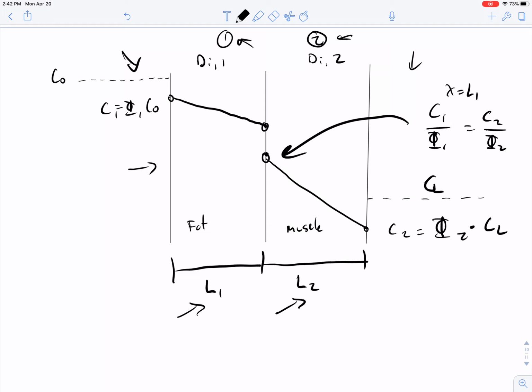What do we do in the middle? What do we do where these two materials meet? We have a balance of partition coefficients there instead of a balance of temperatures, or of concentrations. Remember, with the thermal calculations, we always have temperature equality. Well, we have to have that slightly perturbed here by these partition coefficients at the jump at the interface.